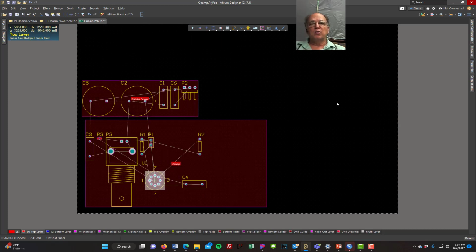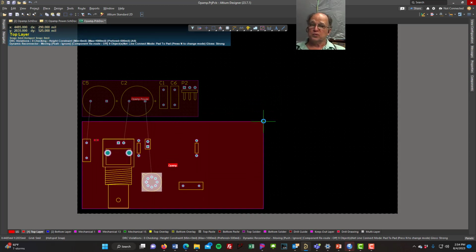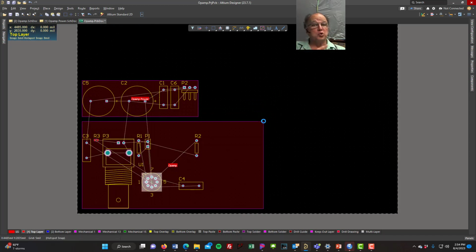And then I can go in there and say, with Altium, I want you to duplicate this room and make all the other 15 rooms look just like this room. And it will. It'll change the shape. It'll change the orientations. Even if it's routed, it will route it like that. So now all 16 rooms look the same, and they're all routed the same. You can then take your rooms and line them up like this. So that's another useful part of Altium, using rooms.